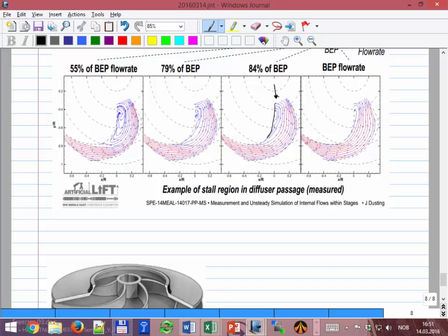The thing is that this angle is only achieved at one unique flow rate. This angle is given by a velocity, and a velocity is rate divided by cross-section area, right? So we cannot have multiple angles. We cannot mechanically rotate these angles to adapt to the flow. They have to be fixed.